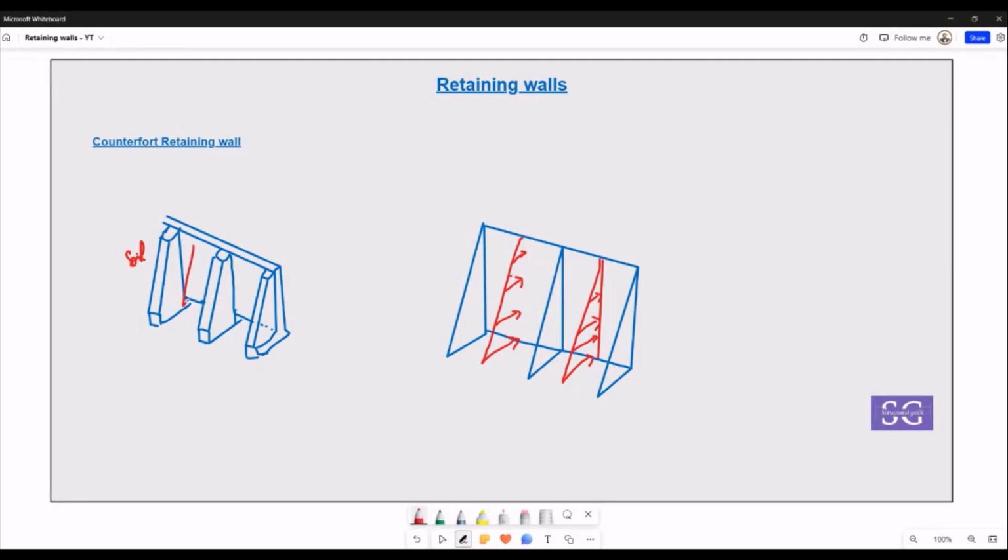Whatever forces are pushed from the soil side, earth pressure, live load surcharge, here is how it happens. Let's say we have a very long retaining wall, and it starts to deform in this direction as well. Right now, when looking at the retaining wall, we mostly work in a 2D fashion, only looking at how it behaves along the height. What about the length? Along the length, the retaining wall can also bend when it is being pushed over a longer span, and that could create a problem.